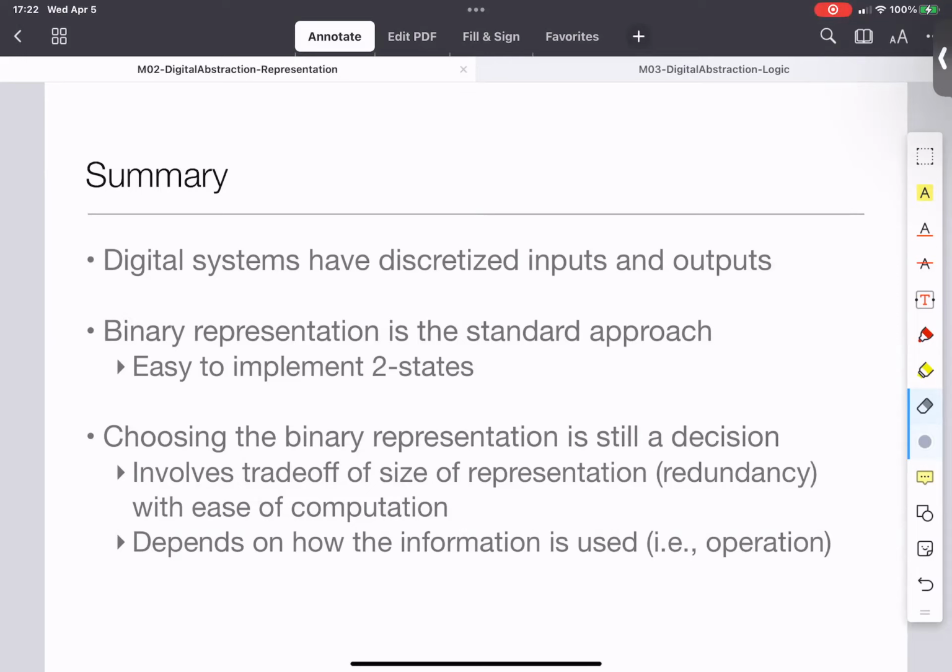signals from higher up kind of map back. Actually, like how in movies you see the fans rotating in the reverse direction. That's an example of aliasing. What is happening is that the movie is taken with a particular frame rate, which is lower than the wheel speed, and so therefore the wheel appears to go back. Unfortunately, when aliasing happens, in some cases, if you know other things about the signal, maybe you can still undo the effect of aliasing.